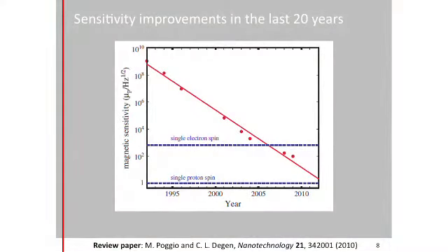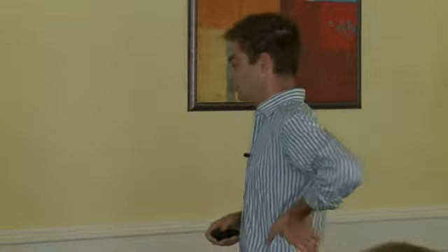And it progressed quite a bit over the past 20 years, with a big milestone in 2004, where the IBM group was able to detect, using this MRFM method, a single electron spin inside of a dangling bond in silicon oxide. And you can see here the basic setup. You have some compliant cantilever, some magnet. You have your single spin over here. You address it with some NMR pulses, and you measure the deflection of the cantilever with an interferometer.